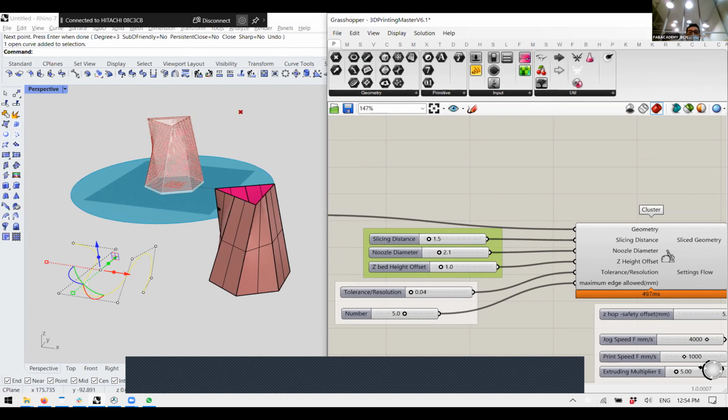go to manual control and home. The machine knows where its home is, so we can move slowly until we measure where the touching contact is on the surface we want to print. We can also control the extrusion here, which we do with the fan. So the machine is going to be doing this all the time. And you see the cartridge, you see the pressure.